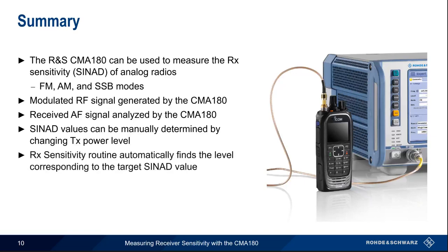This process can, however, be automated using the RX sensitivity routine, which automatically increases the output level until the target SINAD value is obtained. This concludes our presentation, Measuring Receiver Sensitivity with the CMA180.